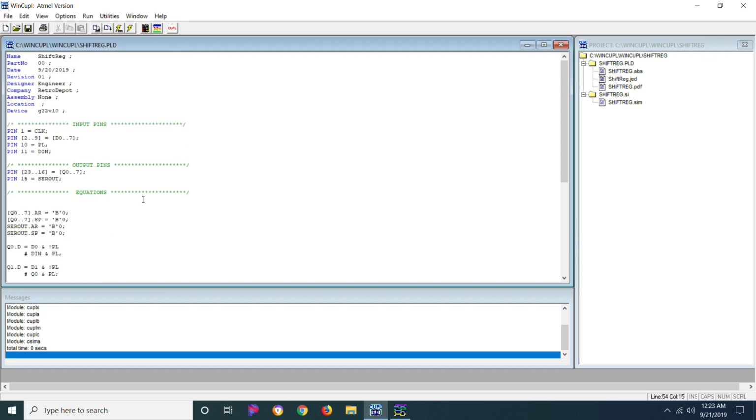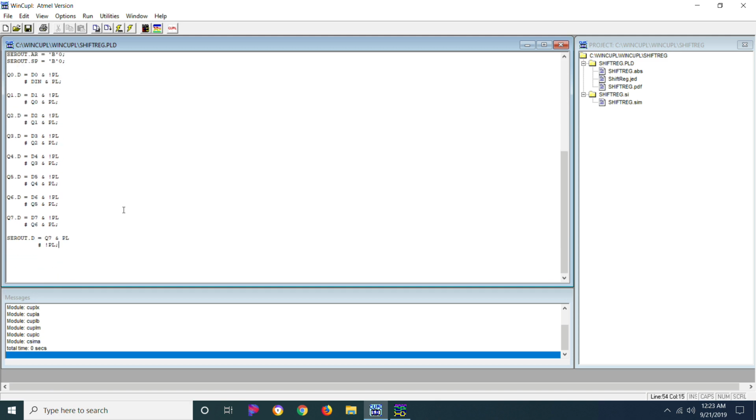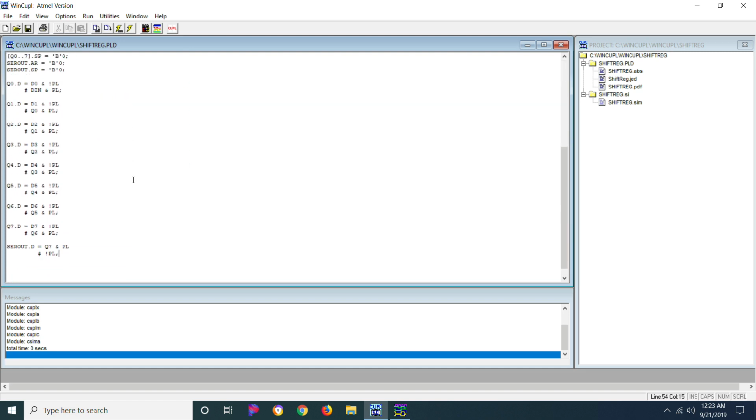I don't know, you may need a shift register and not have one on hand. But we can also change this as well. So if we wanted to shift this out least significant bit first, we can change up the order and have the serial output read from Q0 and Q1 read from Q2, and there's a couple different ways that you can do that. And if you do it the right way, you could probably either make it shift left or shift right if you wanted to, but whatever the case, the basis is there, and now you understand a practical application for programmable logic.